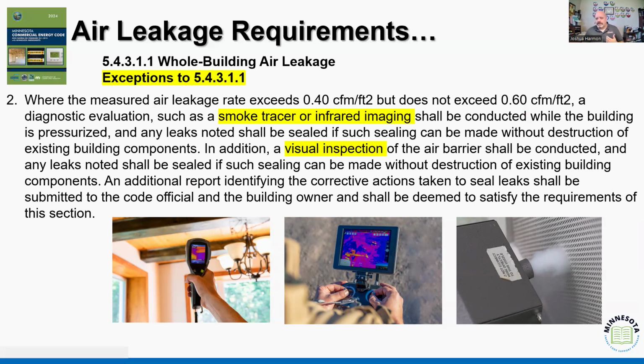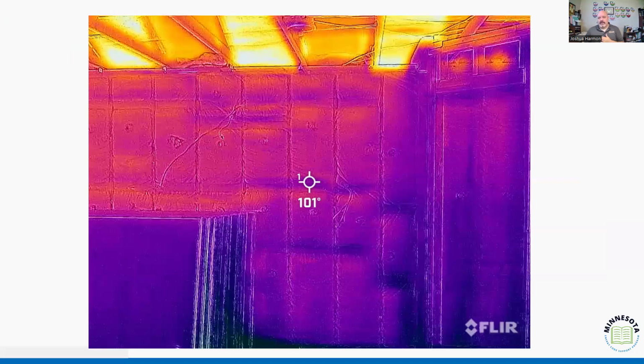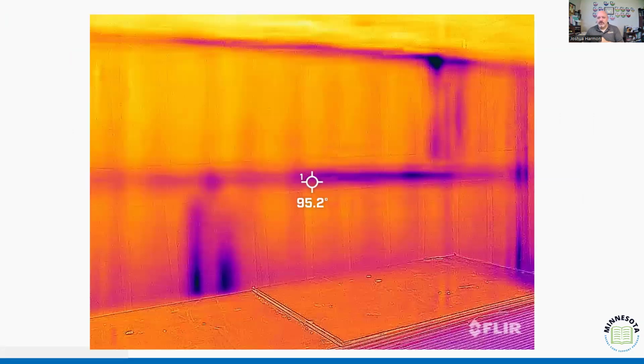And so again, what they're going to be doing is running that visual inspection. They're going to be identifying those deficiencies and then verifying that those deficiencies have been addressed. That comes back as a report to the building official saying, hey, we came close, but we double checked everything and we came back with good answers. So that, again, we can say, do I have, maybe this is where that drywall or that insulation stops, right? So I'm having uncontrolled air leakage. Or again, am I getting thermal bridging? Am I getting a hole that's leaking air?